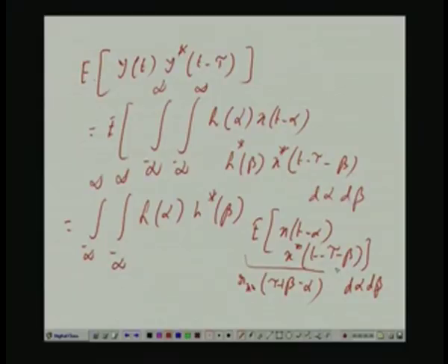If that be so, then what is the output power spectral density? Remember, power spectral density needed the WSS assumption, that is, the correlation should depend only on tau, and then only you take the Fourier transform with respect to tau. If it is not stationary, there is no question of power spectral density. So, the WSS nature is a must. The autocorrelation should depend only on one variable tau, and you take the Fourier transform with respect to that variable. That is what is happening at the output. So, I can find out the output power spectral density.